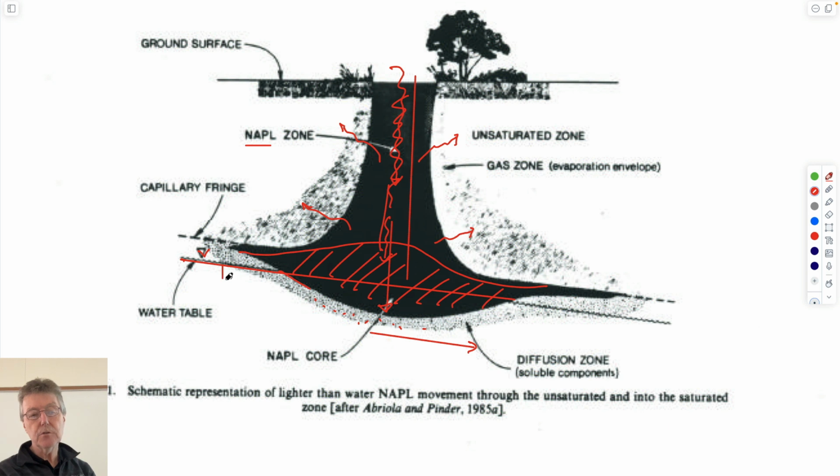In this particular case, the water table has a gradient on it, dH/dx. The head, remember what hydraulic head is? It's pressure over unit weight plus elevation plus v squared over 2g.